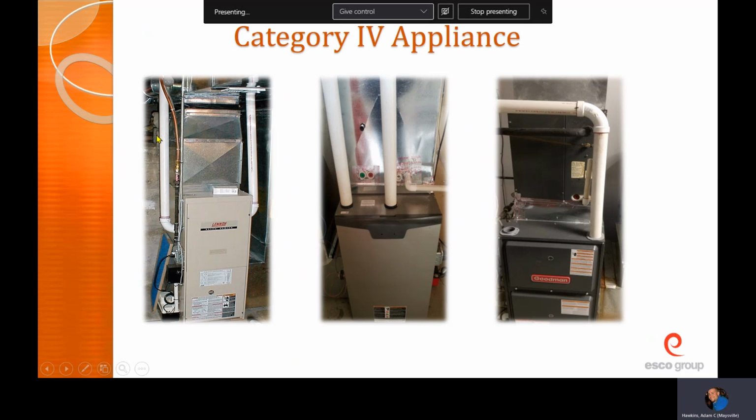If you have a furnace that is in a fairly confined space, and honestly, when you actually do the math on how much combustion air you need, it usually needs to be a bigger space than what you'd originally think to have enough free air available for combustion. So if this is in a closet or a mechanical room, something like that, you're going to need to pipe in outside air. So you're bringing in fresh air and then you're exhausting your combustion air. This one on the right, they apparently have enough free space. Maybe it's in a basement or something. And so they're just drawing it from the room and then venting back outside. So they've only got one.